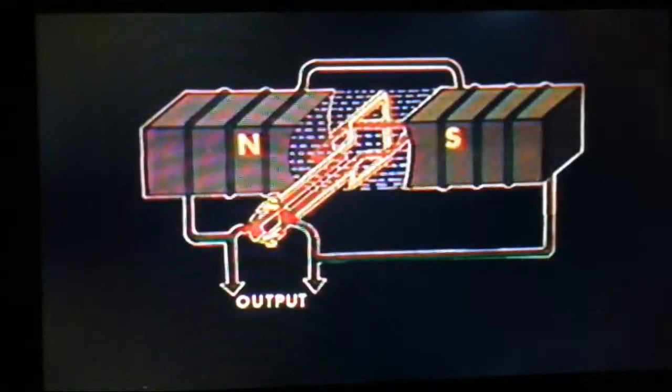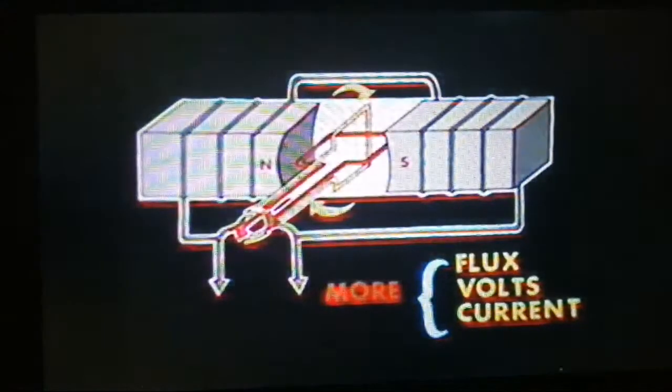For the same reason an electromagnetic field in the AC unit is used, the poles or field coils of the DC generator will be electrically magnetized and controlled. DC voltage excites the field coils. Once a DC voltage is generated in the rotating coil circuits, connections can be made to the field coils. These are self-excited fields, but as the output voltage increases, with speed of rotation for instance, more current is forced through the field coils, creating more magnetism, which in turn creates more voltage output, and on as long as the mechanical energy driving the unit can supply necessary forces to rotate the coil loops through the heavy flux lines.